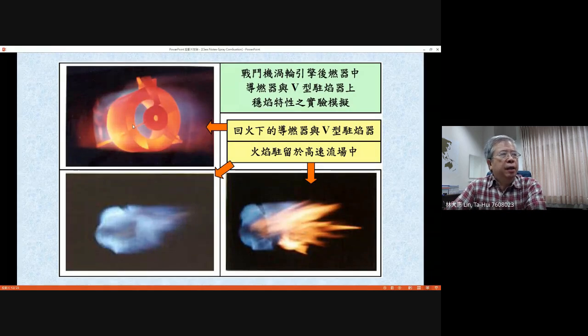But in many aircraft, they use liquid fuel injected to produce a spray flame. And there is a V-gutter, as I mentioned, because the flow velocity is very fast. Then you need some bluff bodies to produce a flow region with lower velocity, and the lower velocity is good for stabilization of the turbulent premixed flame. Here the V-gutter is used for flame stabilization.